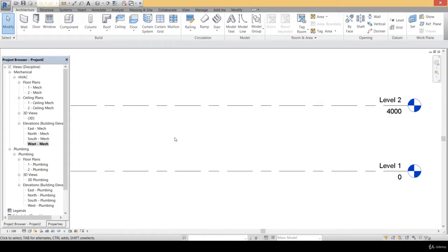Now let's start with the first step of our project, which is to add an architectural drawing inside Revit. That's logically the first step of the practical design, as our work as HVAC designers starts when the architectural designers finish their work or their architectural layout, with the specification of the dimensions, the direction of the walls, and the position of the building.